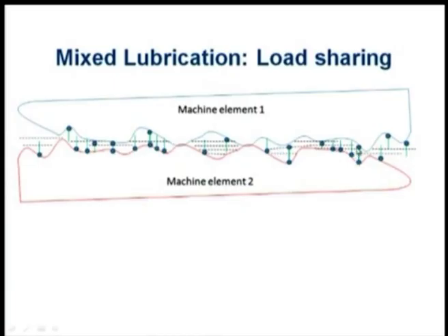That means, there is a possibility of dry friction without any boundary additives. There are a few contacts with the boundary additives, few contacts with liquid lubricant, and few contacts where elastic deformation has happened. You can see this surface is elastically deformed. It is showing a much smoother surface compared to the valleys and peaks which are shown on the other surface. Similarly, there is elastic deformation over here. So, there is elastic deformation, there are boundary additives, there are liquid interfaces also, and there is dry contact. This is why we are calling it mixed lubrication.